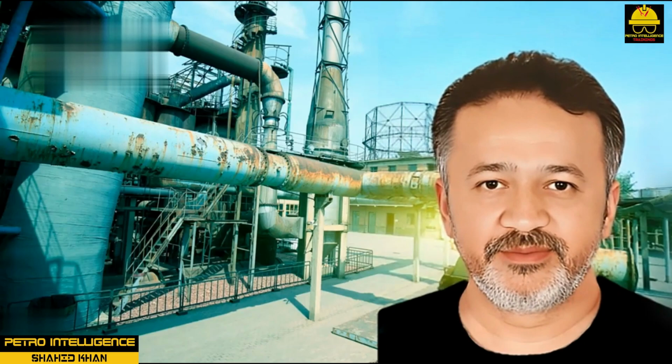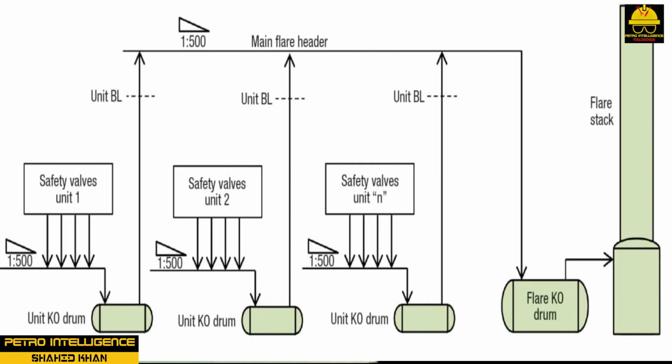Relief system. The discharge from all safety valves, pressure relief regulators, and operating vents and blowdown valves in hydrocarbon service are collected in a closed piping system and sent to a flare stack. Steam, air, and nitrogen vapors discharge to the atmosphere. Steam safety valves discharge through tailpipes at a safe distance above grade or above the nearest operating platform.